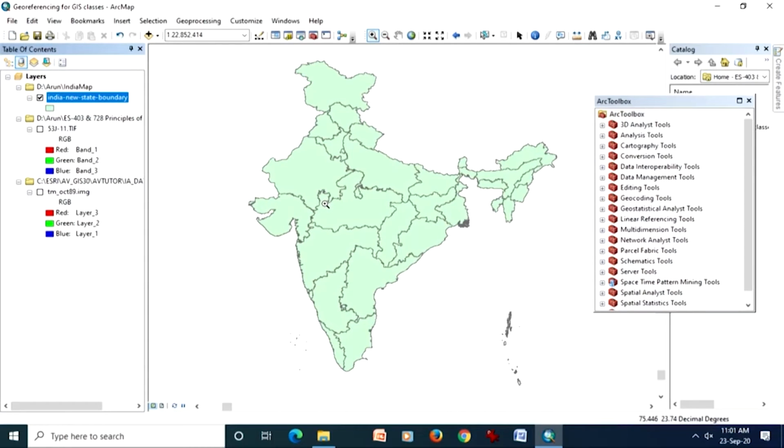Automatically, the file which is first in my project, the next input file will follow the projection system of the already existing file, and this is called on-the-fly projection. This will speed up our georeferencing as well. If files are georeferenced but have different projections, the software will take care of this, and this on-the-fly projection facility is now available in many software packages.